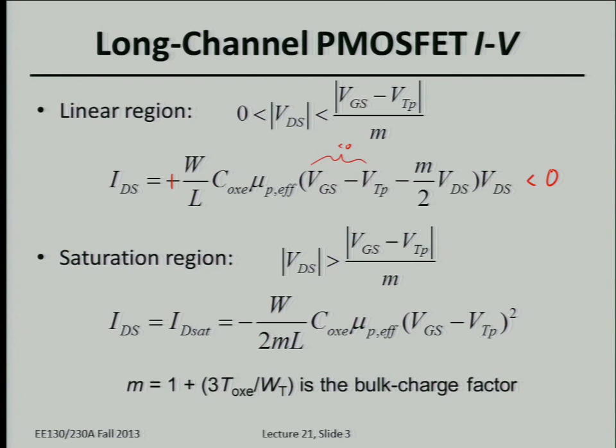And then in the saturation regime, again, the maximum voltage you can apply across the inversion layer of holes, in this case, is just VGS minus VT, corrected by that body effect parameter. Okay, so the equations look very similar. Just keep in mind we're applying a gate voltage that's lower than the source voltage, and the current is not flowing into the transistor, into the drain. It's flowing out of the drain. Okay? All right, just qualitatively, are there any questions?